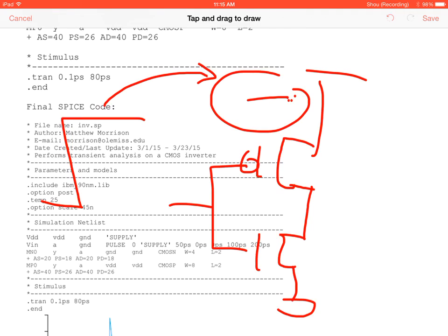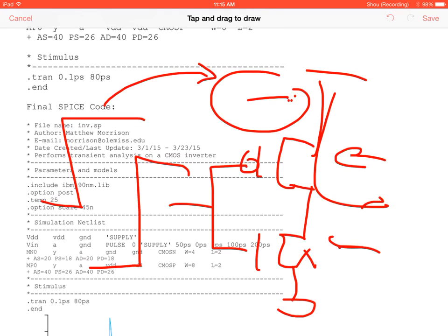It turns on the NMOS... it turns on the PMOS, turns off the NMOS. Right, so this is on. So what's physically going on when they're on and they're off? The channel's created. Yeah, we have our channel created here, and the channel is cut off here.